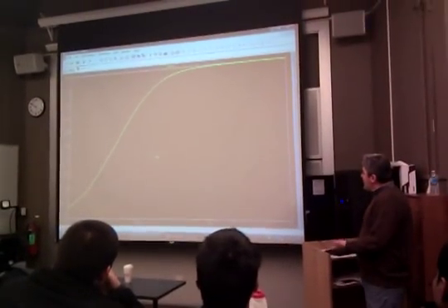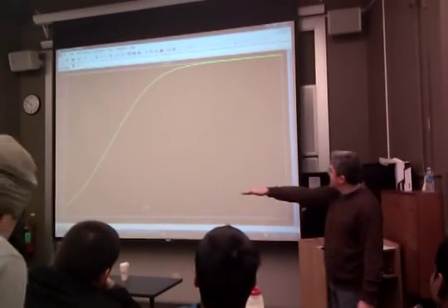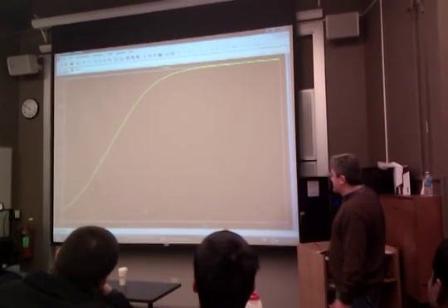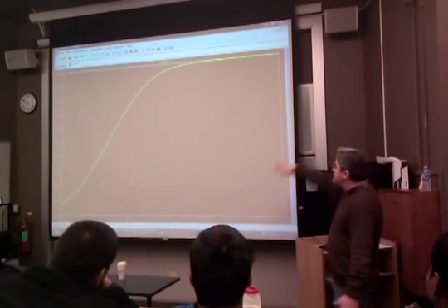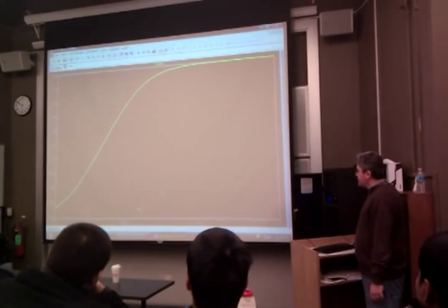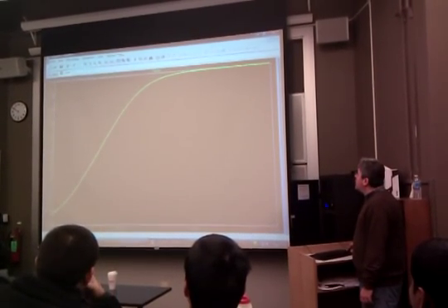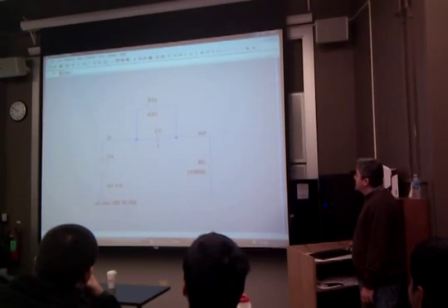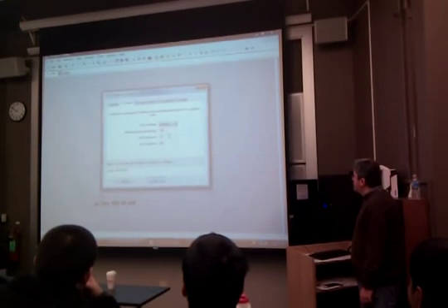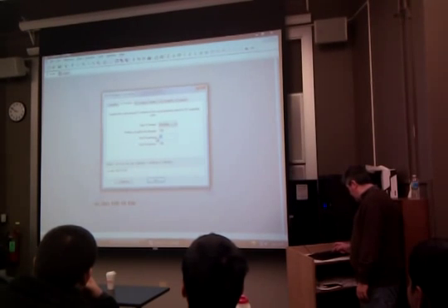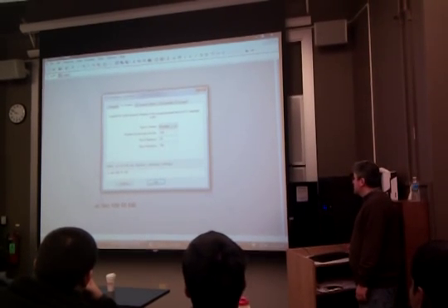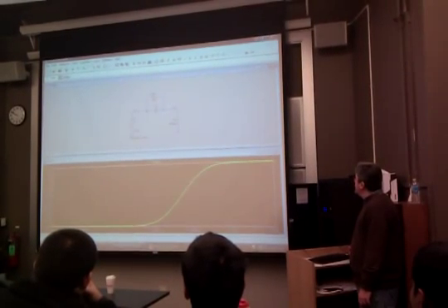But by the way, you say, well, I don't see this flattening out, right? So you can truly go down to minus 20 dB, so 0 dB in this case. So what you might want to do is go back to the simulation here, okay, and say, I want to plot for even lower frequencies. I want to go to 0.01 hertz. Okay, hit OK, and run, the running guy here, and there it is, right?